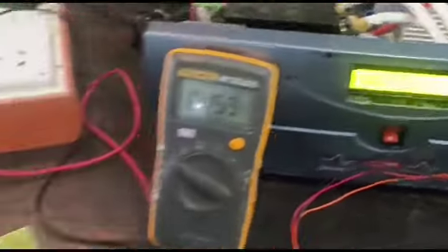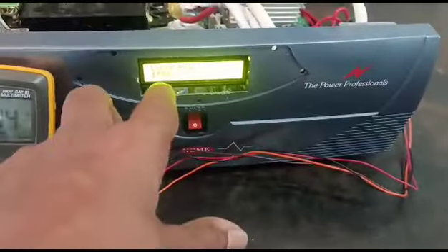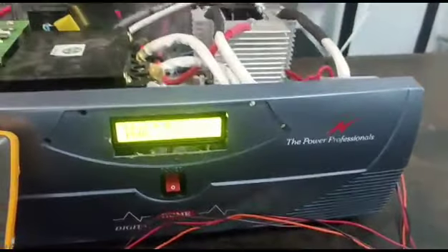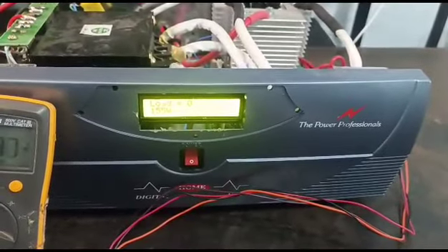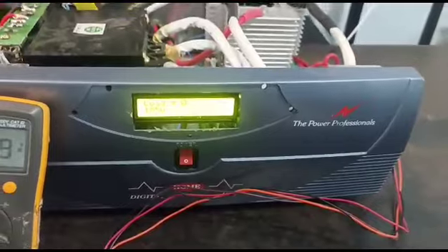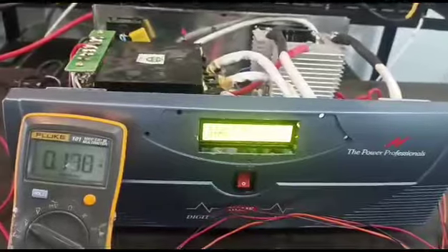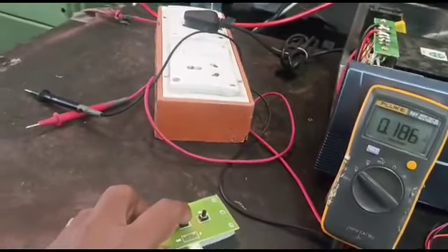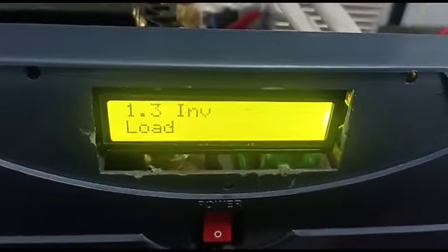So now again you press enter after doing this setting. If any wattage is showing wrong, you have to calibrate it. For example, for a 200 watt bulb it shows some 250 watts. You have to reduce it using the down button and correct it. Then you have to save it. Press enter. So now it is saved. Next option.